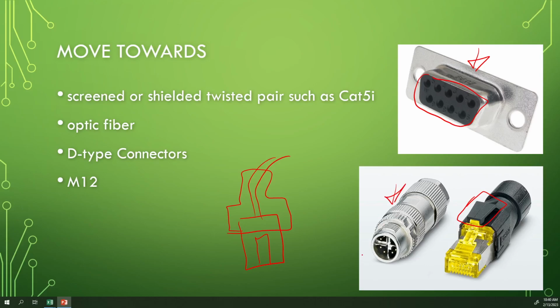So this is widely accepted in the fieldbus and automation applications. If you look really closely, you could count the terminals. So there are 2 terminals per quarter, so there's 8 terminals in there. This does offer excellent protection against moisture, dust, corrosion, EMI, RFI, mechanical vibration, shock, UV radiation, and extreme temperatures. That's a mouthful. That looks like a pretty ballsy connector, doesn't it?